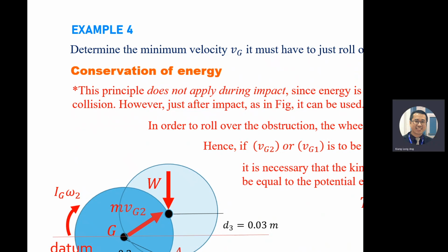So when you take energy into consideration, you look at potential and kinetic. So number 2 and number 3. Okay, so then you put in kinetic equal to half mv square. Again, this is a rigid body, so you have one more kinetic term, half I omega square. You don't see this one in the particles chapter, but when you come to chapter 6 onwards, you will start to see half Ig omega square. Right?